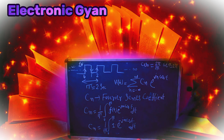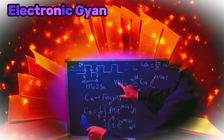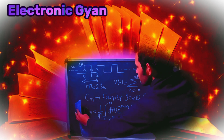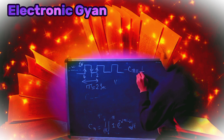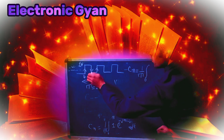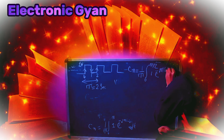Now we have to integrate this and we will get the Fourier series coefficient. Then we will put this back and get the actual voltage. So now I'm going to rub this here. Cn is equal to 1 by T, integration 0 to T by 2, because for the total period T the pulse is 1 up to T by 2. So I can write T by 2, 1 into e to the power minus jn omega naught t dt.